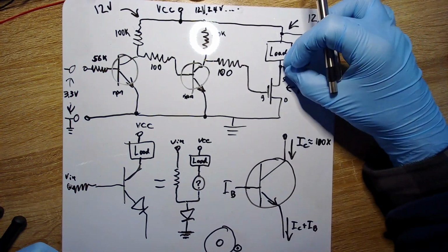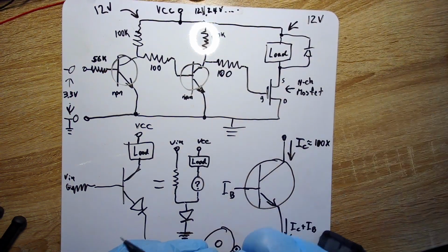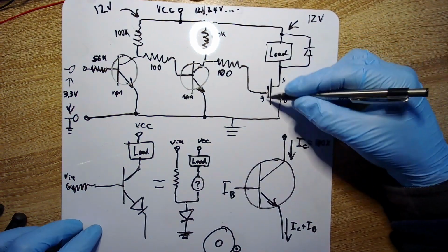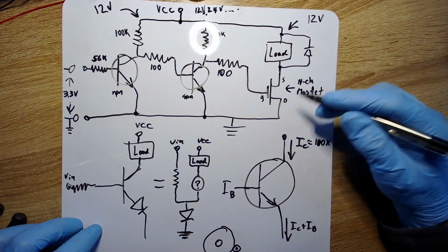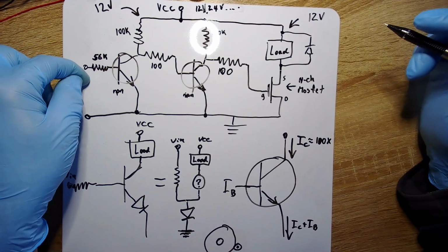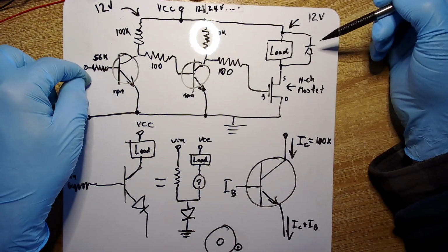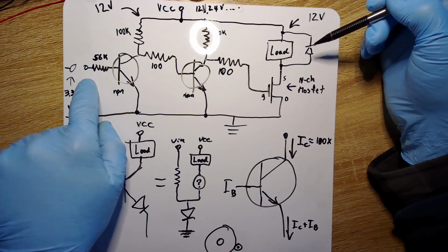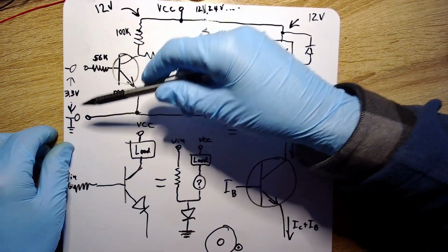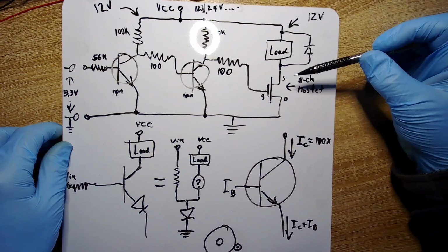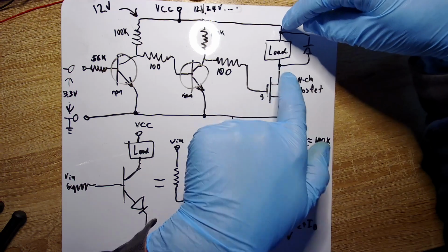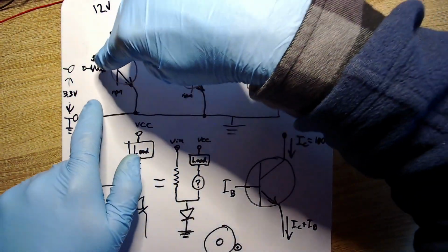We could just disconnect this and just connect the load to ground if we wanted to, right? And a lot of times if we're testing, that's what we will do. If we're wondering if this is any good, we will connect to ground and see if that load works. Or maybe the computer's bad, so we disconnect the computer and connect up to the beginning of the driver and see if the driver works. That's something you almost never see people try. It could be impossible. This may be a connector right here, or this may just be on the circuit board. Your connector may just be this right here, so all this stuff may actually be on the circuit board, which is tough.